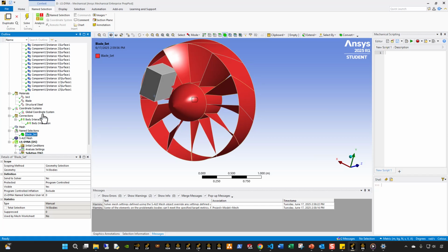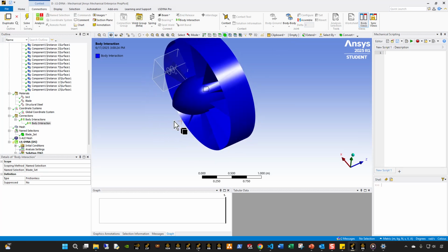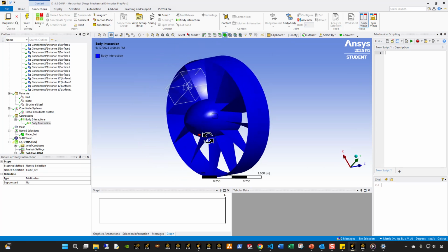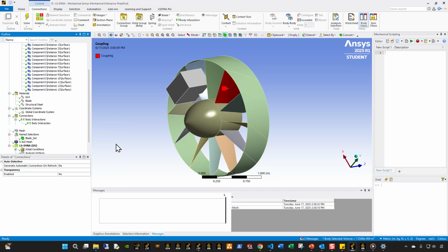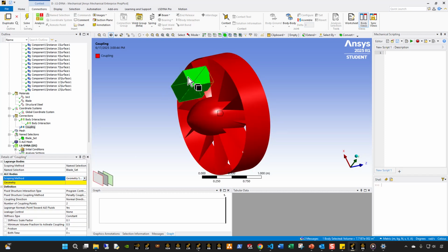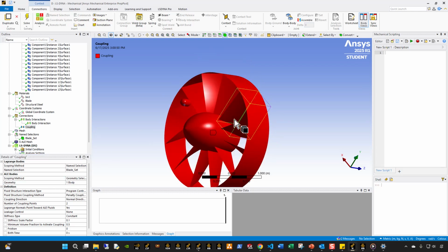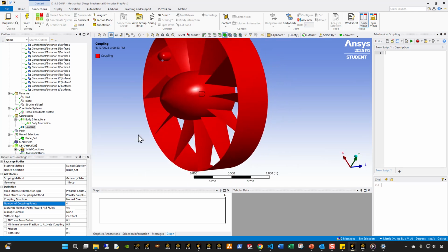Okay, so that's actually going to be assigned to this body interaction, and that creates a single surface body group, a contact group, which basically allows, when the blade itself breaks apart, the pieces to see each other as a contact pair. The next thing we want to do is define a coupling, between the Lagrangian body, which is the blade set, and the Eulerian body, which is going to be our water piece. And I'm gonna set this to 4, and that basically defines my coupling piece, right?